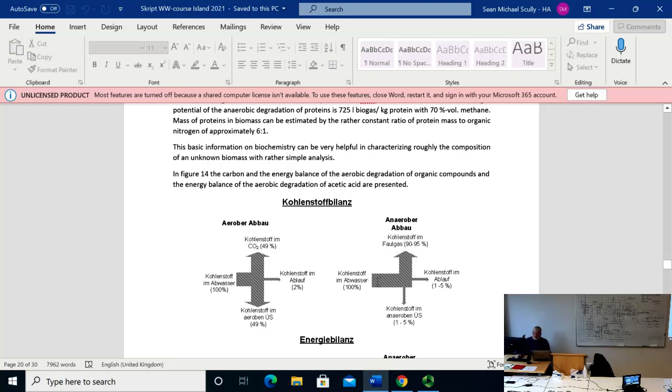So those guys live off very little energy for themselves. They don't have sufficient energy. And we know from composting that you can even heat up the mass considerably. And you can always do liquid composting and sludge. If you have 5% sludge, you will heat it up to 60 degrees centigrade easily if you aerate it, whereas you almost have no calorific change in the anaerobic degradation of sewage sludge of the same concentration.